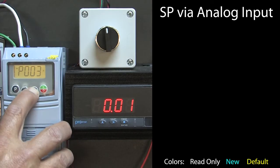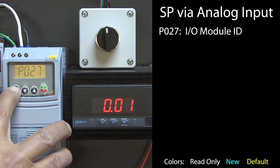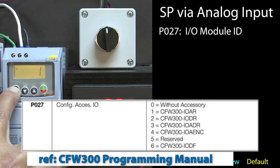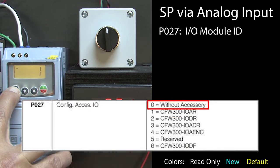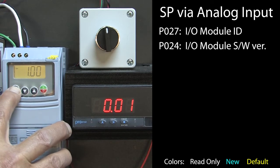Okay, let's fire this thing up and go view parameter 27, which tells us if we installed the module correctly. Yep, I see a 1, which is this I/O module. I got that from the drive's programming manual parameter listings. Now if you see a 0 here, then something's wrong. Go take a look and make sure those pins didn't get bent. You can also see the software version of that module in parameter 24.